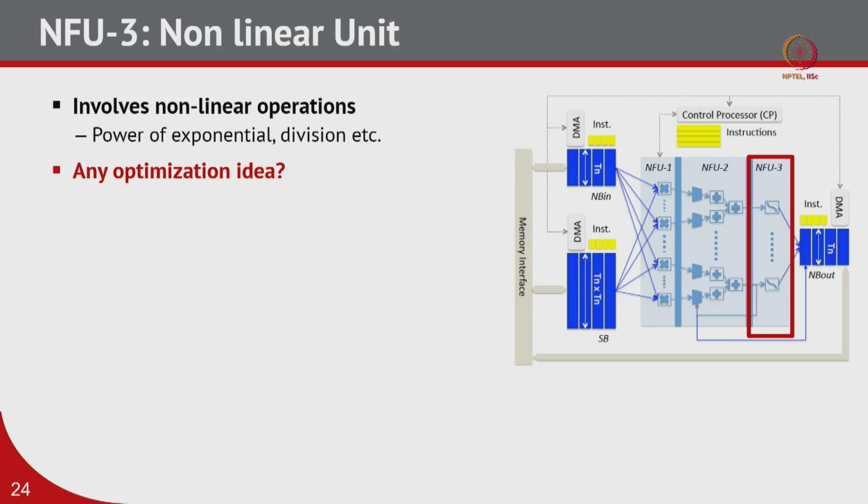Now, remember, hardware is nothing but logic gates, right. They can have AND or NOR gates. From all those gates we can have adders, multipliers, those basic arithmetic operation units, right. Now, with those units, how can we build a nonlinear unit, or how can we perform nonlinear operations? So, in this particular accelerator architecture, the nonlinear unit is implemented as a piecewise linear function.